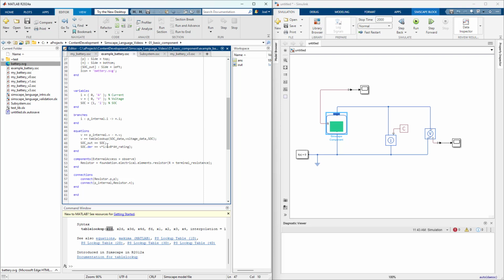There's always certain scenarios where there's an effect that's happening to your component that's making its value or its behavior change that just doesn't exist in existing modeling components. And oftentimes it can be represented with a lookup table very simply. It lets you give very accurate, very fast results without having to do any complex math.